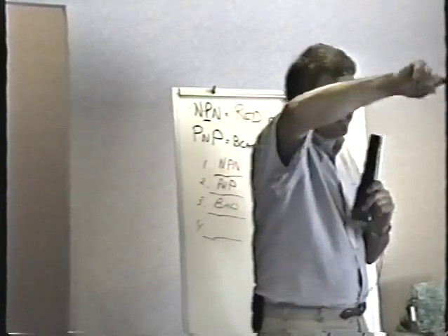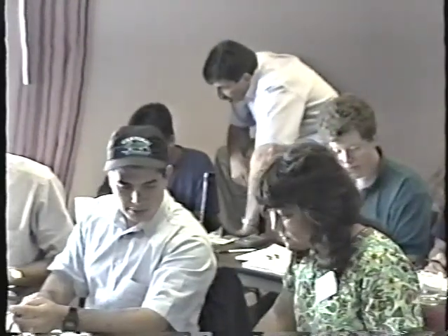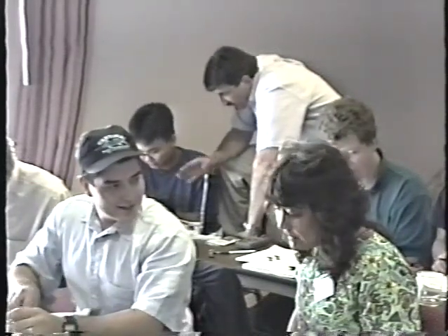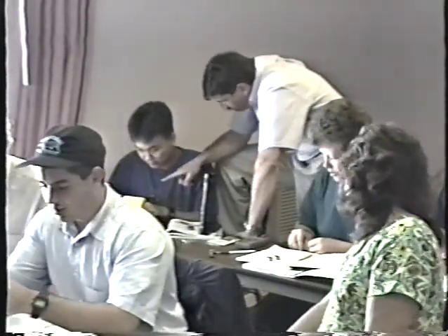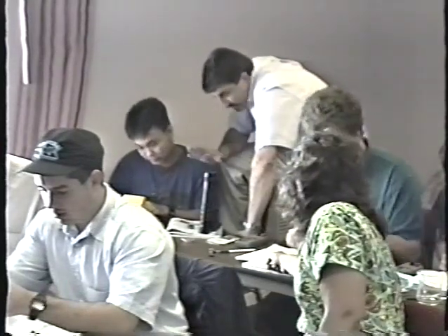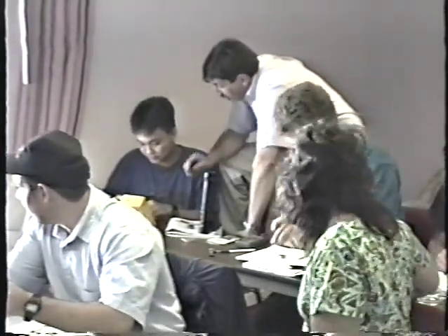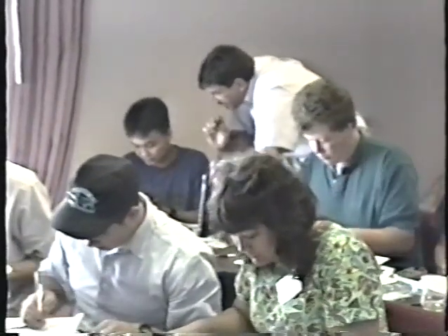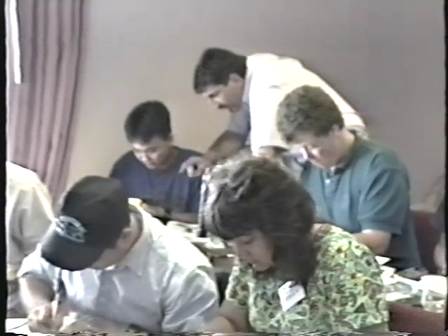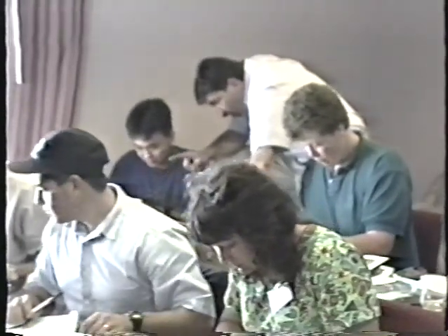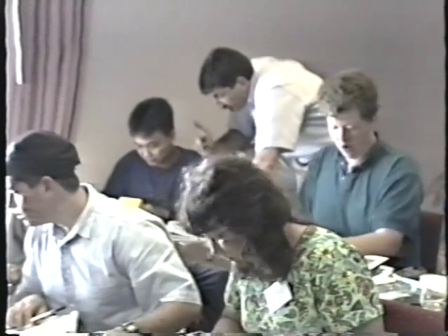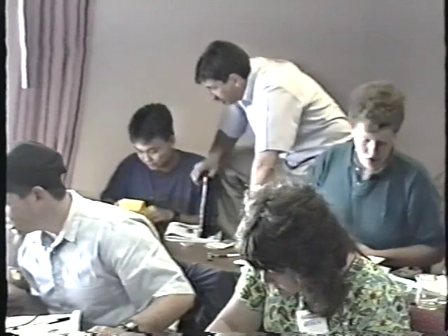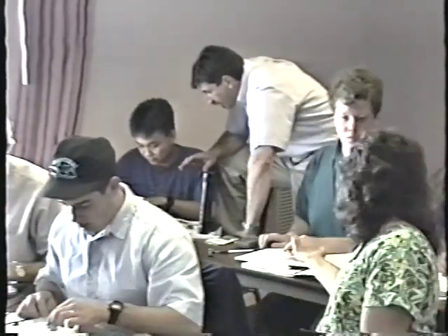Now I'm going to circulate amongst you. Okay, yeah. Start with the red on the base and the black on the emitter. You're getting a junction drop, 0.5. Leave the red exactly where it is. Don't move it. Move the black to the collector. 0.5. Same thing. So far, so good. Now leave this the way it is. Reverse the leads in your hands. Do the same thing you just did. This time we should get an open reading. Yes. Open. Open. Now, final check. Collector to emitter. Very important. The collector, which is the case, to the emitter. Doesn't matter which lead you put where. Should be open.